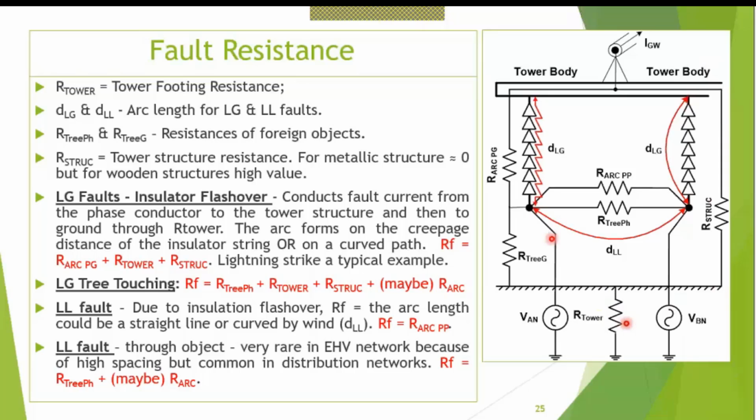No problem. Now there are two kinds of faults. First of all, let us take an LL fault, that is easier to understand. An LL fault can happen when there is a flashover between two phase conductors. So what is involved? Only the resistance of the arc.